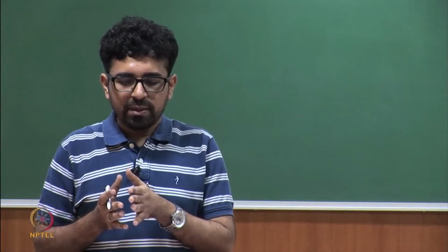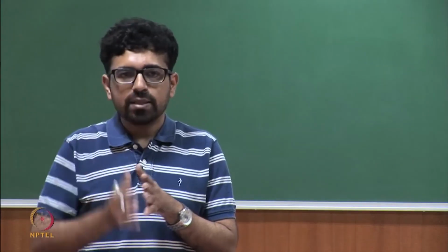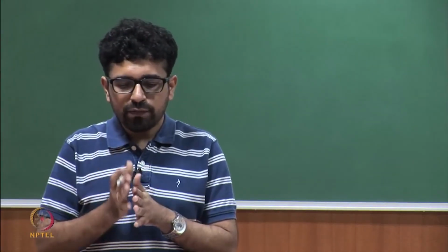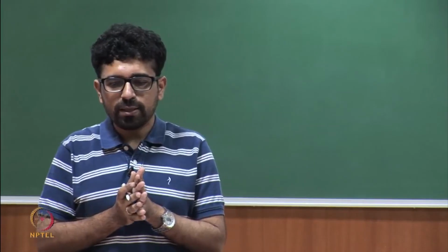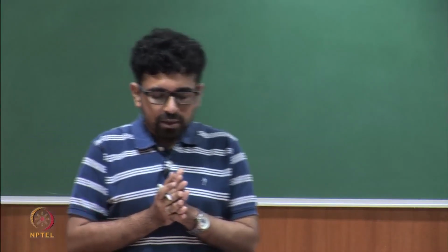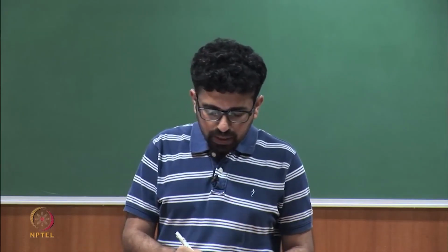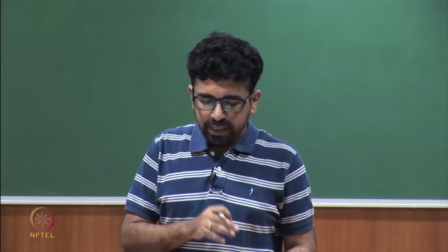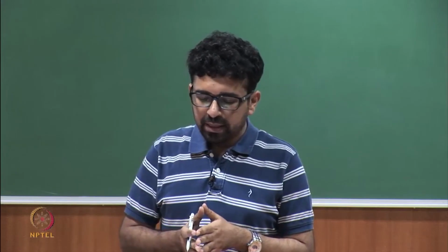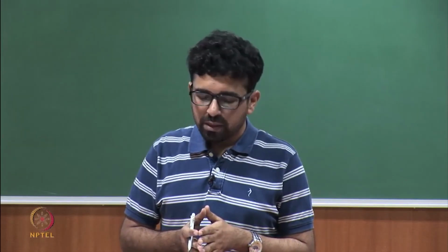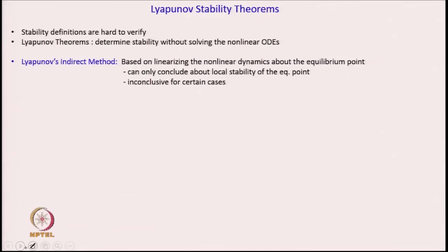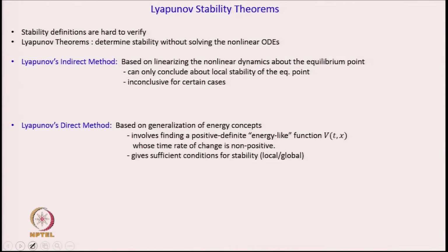However, if any of the eigenvalues has a real part which is 0, that is, any of the eigenvalues lies on the imaginary axis, we cannot conclude. So, although this method is useful because it takes you to the linear region, and then you could look at the eigenvalues, it is inconclusive for certain cases, and so Lyapunov's direct method is a more general method